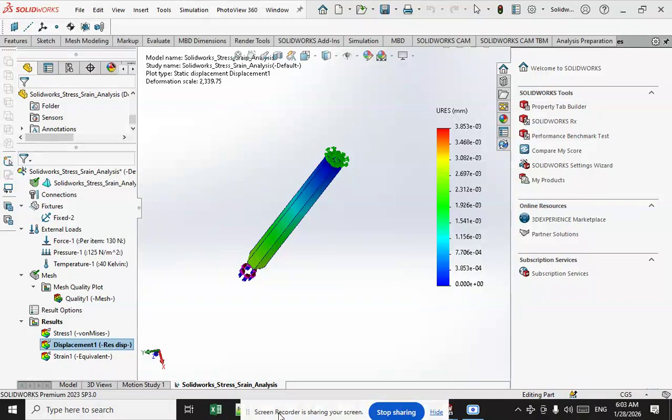The analysis allows for a rational method of defining the material strength and results in a value less than, for example, 99.99% of the values from the samples tested. By that method, in a sense, a separate factor of safety has been applied over and above the design factor of safety applied to a particular design that uses said material.